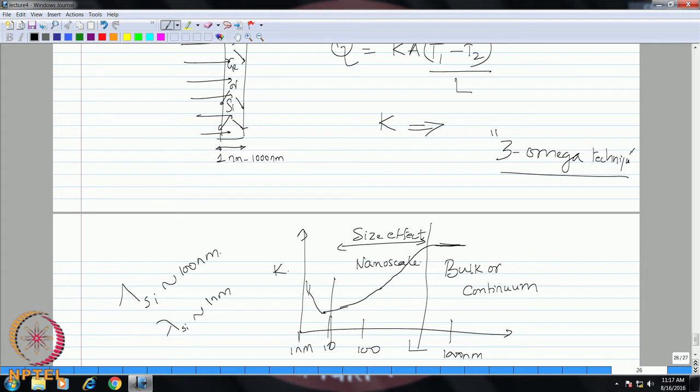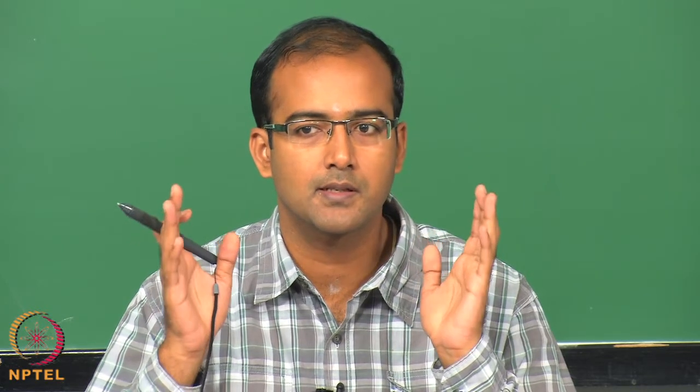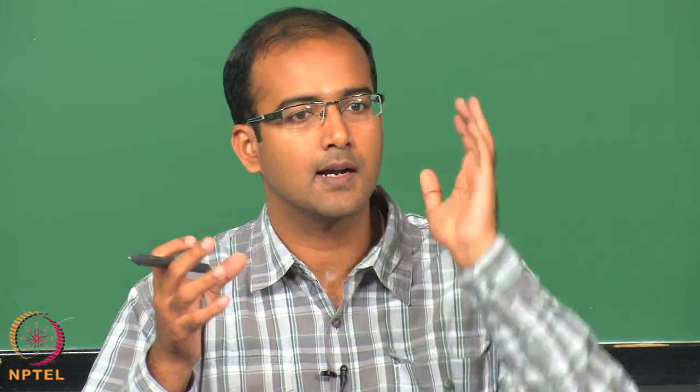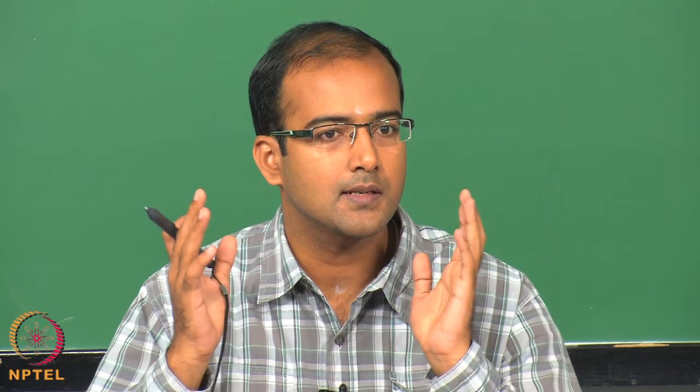So, in this case therefore, there will be a lot of temperature jump created at boundaries, because the boundaries are the sources of non-equilibrium. Okay, you are fixing the temperature at the boundaries, but this is not what the actual temperature of the energy carriers is, because the energy carriers do not have enough number density to sense this temperature at the boundaries, because this temperature can be sensed only through the diffusion process. And since you have only very few energy carriers left, they directly come and hit the boundary and then realize this boundary is at this temperature, but by the time it is too late, and there will be an artificial temperature jump, just like you have a shock wave. Okay. So, this is called ballistic transport.